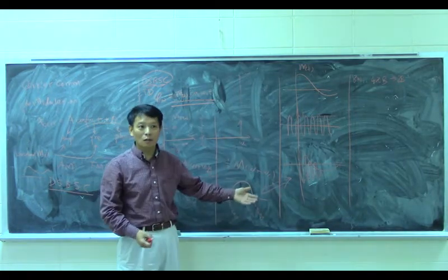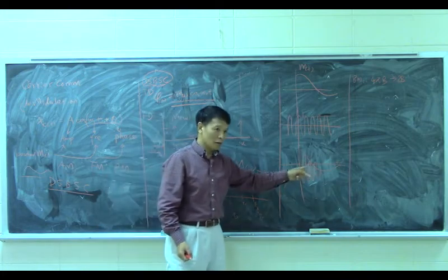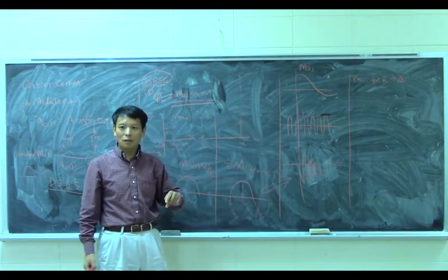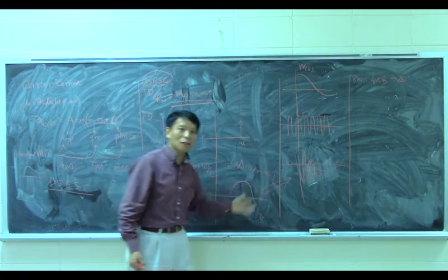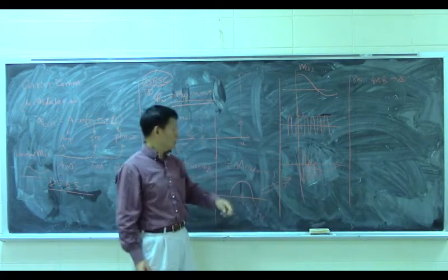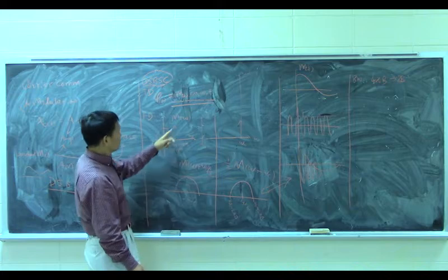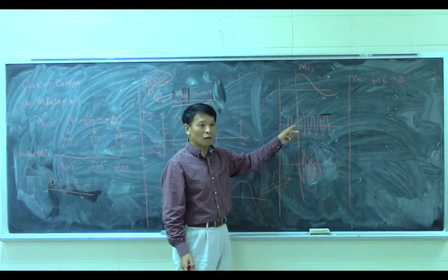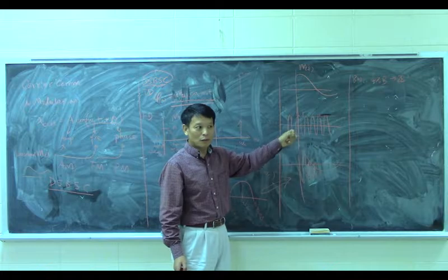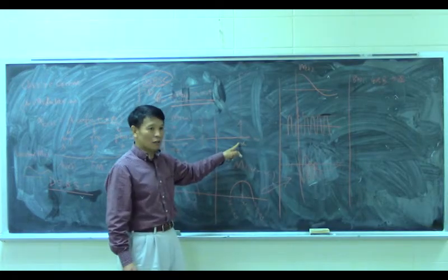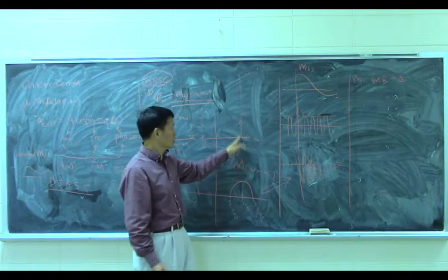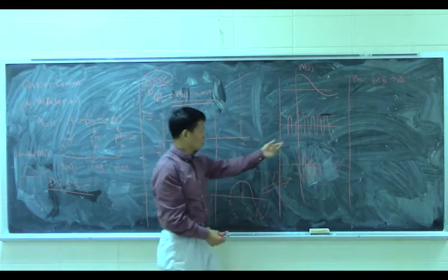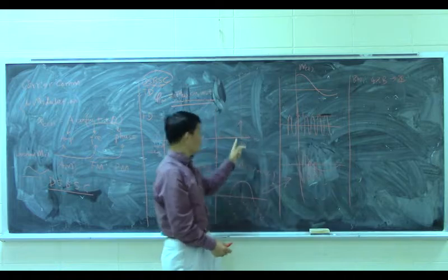For the same signal, if you look at it in time, it looks like this. If you look at it in frequency, it looks like this. Everybody understand this, right? They are the same thing. This one is a cosine function, on the oscilloscope, which you're familiar with. Now this is on the spectrum analyzer. You look at this only at the RF frequency, because we know there's only a single frequency here.